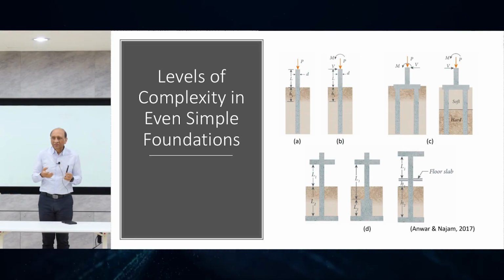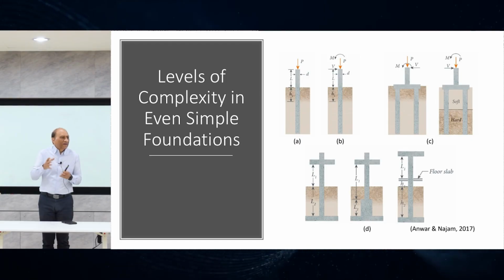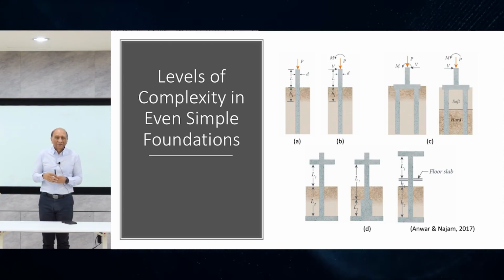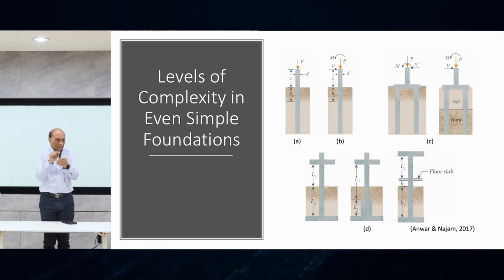That depends, from three to five times the diameter of the pile, depending on the soil. So about roughly five times the diameter, you can assume that the pile has locked, has stopped moving, and that's the location. So that's the effective length of the pile, and that's where the moment should be calculated, not at the top of the pile.